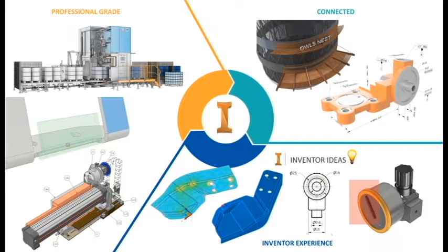Some of the new changes with 2021 is the fact that on those annotations that you see in the upper right of the screen, you can actually attach some notes from, let's say, a model dimension. So you bring that model into a drawing. One of those dimensions, you can actually attach a value into a note on the drawing. So if a thickness or a length or a width updates, you'll see that note on your drawing update automatically. It's not a manually entered field.